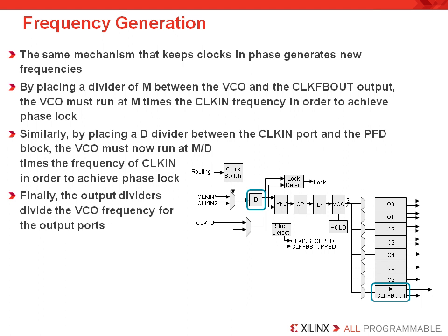A feedback clock is not required, but it could be used to maintain a specific phase relationship to the input clock, which is sometimes essential. Providing this feature inside the FPGA reduces your overall system cost because external oscillators are not required to create the additional clock frequencies you might need.